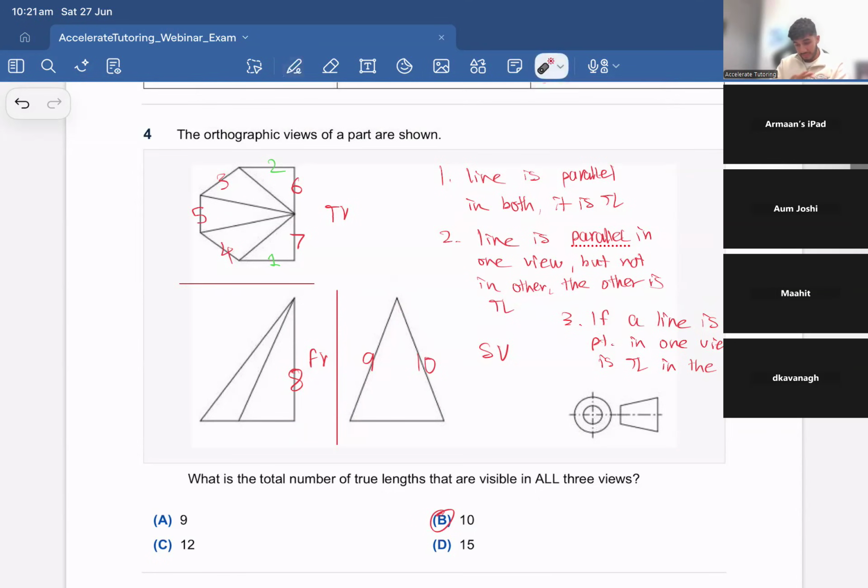So typically, we just have top view and front view. So these 3 rules are the main what you need to do. Just draw a horizontal plane in between the top view and front view. If you're given an orthogonal projection, just draw another vertical plane in between. Same rules apply even for that one.